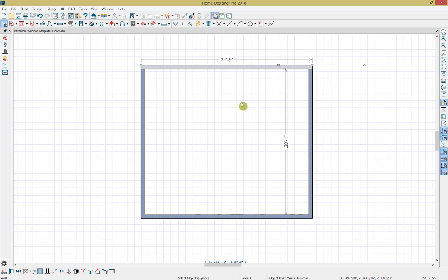Since we already have this exterior wall selected, we see that this temporary dimension appears. When we select this temporary dimension, we'll have the option to change the dimension and move where the dimension will locate to. You can see here right now that it's moving the right end of this wall, so I'll keep this selected and I can type in my dimension of 28 feet.